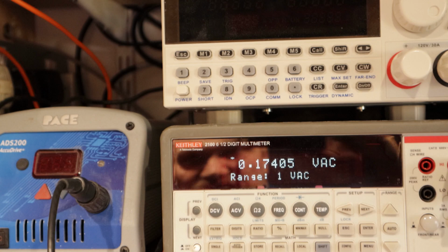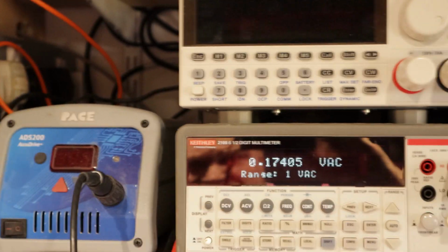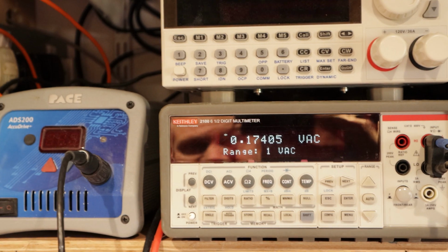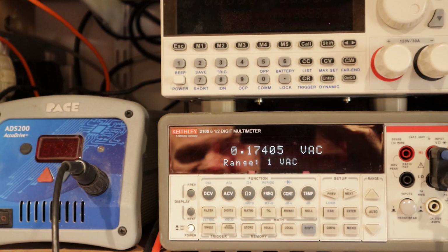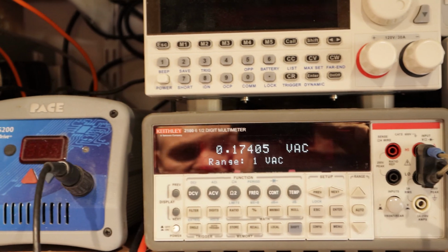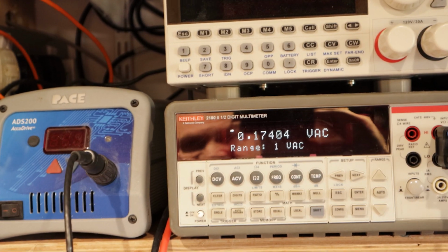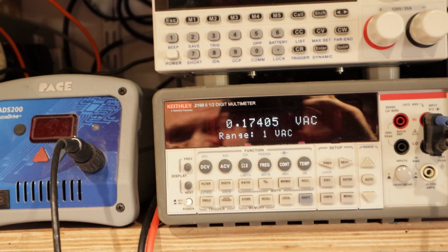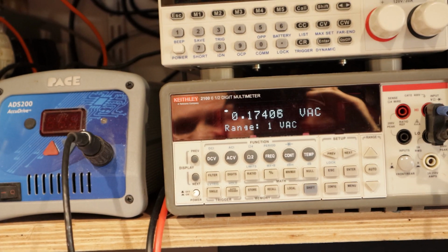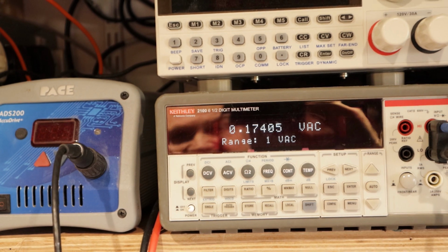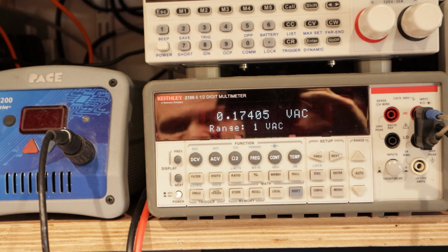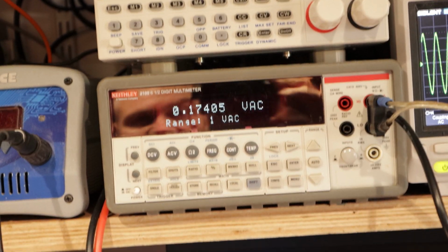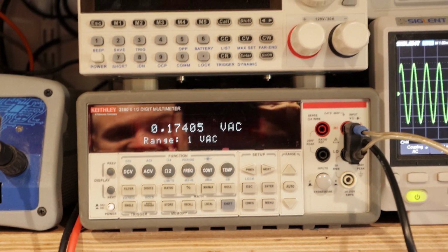So you can see that by using the multimeter, you can actually tell that you have an alternating value, because by switching between DC and AC, you can see that it virtually disappears on DC. On AC, you've got a reading which is quite steady, so you know you have a good repeating pattern, but you don't know what that pattern necessarily is.